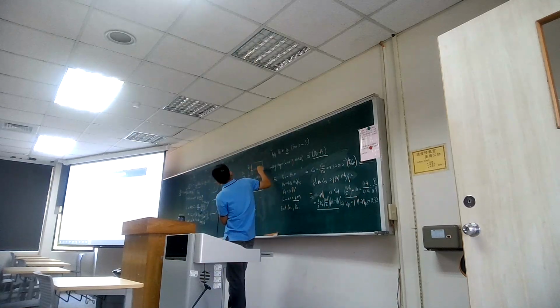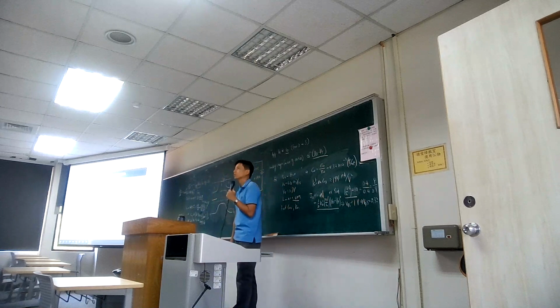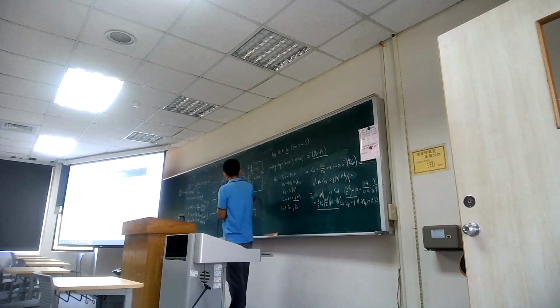If you connect the output here, there's no current, so there's no voltage drop along the resistance. So how much voltage we supply here equals the voltage we measure. So under that condition, that will give you a high voltage at the output. But if you connect with the high voltage as the input, what happens here is you get a large current.